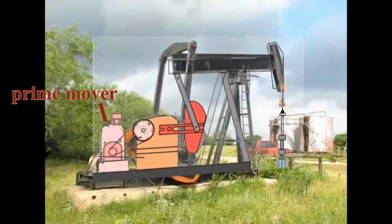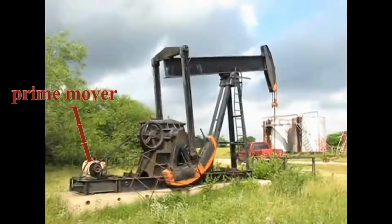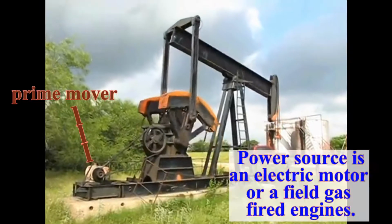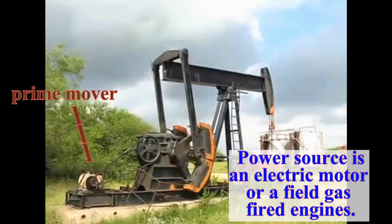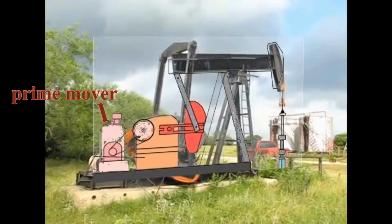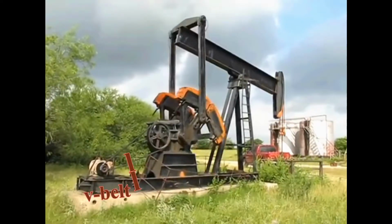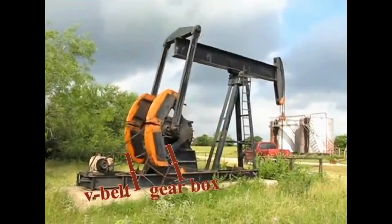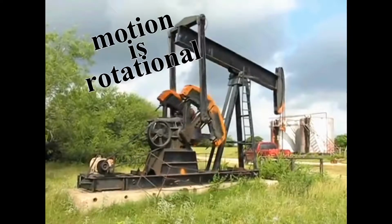The prime mover, located here, provides the power that operates the pumping system. Its power source is usually an electric motor, but field gas-fired engines can also be used when there is no ready source of electricity. The power from the prime mover is transmitted by the flexible V-belt located here. The V-belt is attached to the pumping unit in the gearbox. Note here that at this point the motion is rotational.